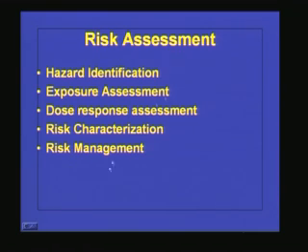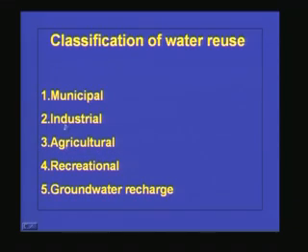So this is essential whenever we go for a water reuse project. The risk assessment is very essential. Now we will see what are the different ways we can reuse the water. One is municipal, another one is industrial, third one is agricultural reuse, fourth one is recreational, and fifth one is groundwater recharge.